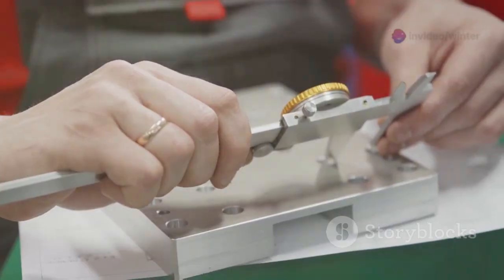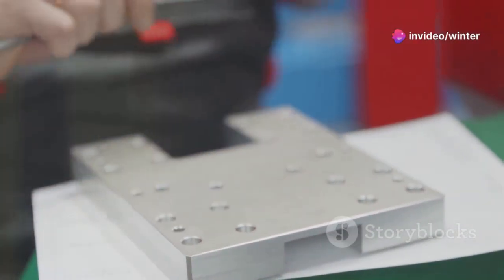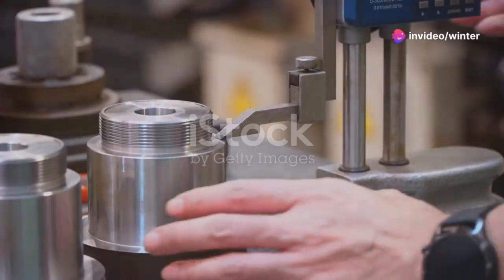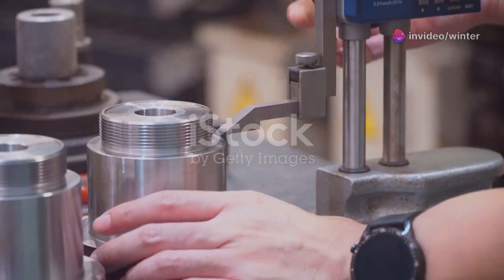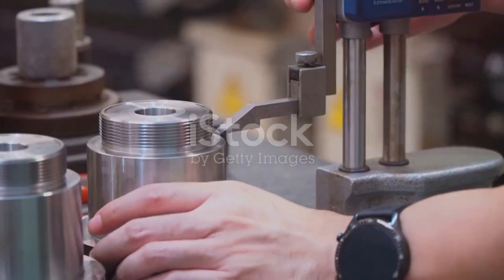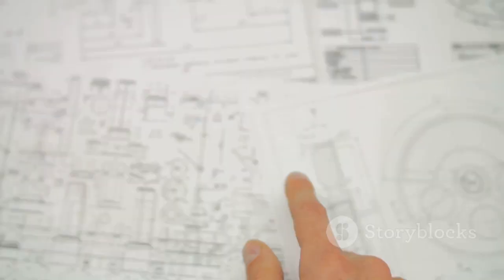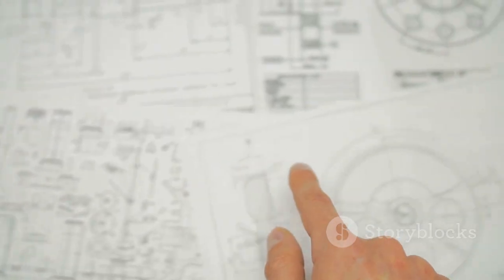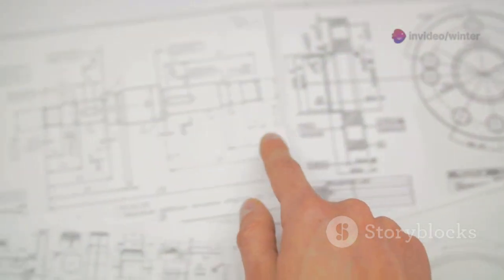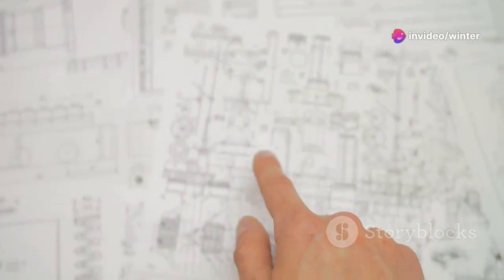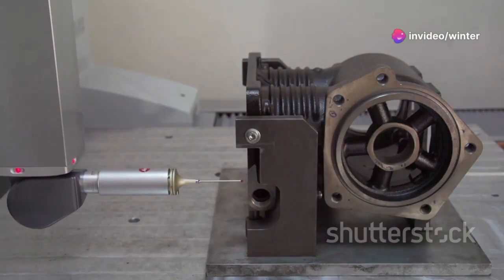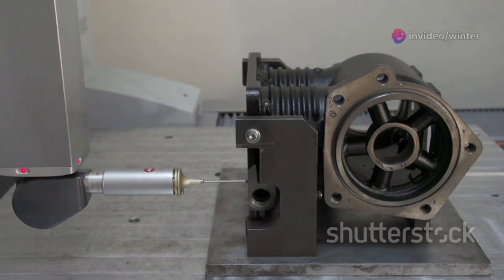Tolerances. Engineers love them, but tight specs drive up costs fast. Every extra decimal means more precise machining, slower production, and higher inspection costs. Only apply tight tolerances where they're truly needed. Critical fits, seals, or safety features. For non-critical dimensions, use standard commercial tolerances.